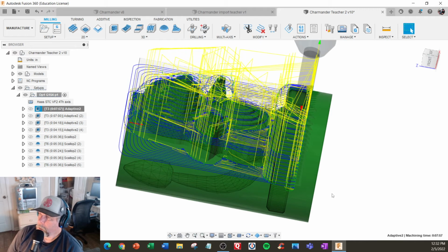So now we're getting into our standard: adaptive for all the roughing and pocketing for a nice looking floor. Because your adaptive is not meant to make nice walls. It's just roughing material. So you want to use contour and pocket for walls and floors. Or you can just use pocket by itself if you turn on finishing passes. So those are the goals there. All right, so as far as time goes and stuff like that, that's pretty much it.